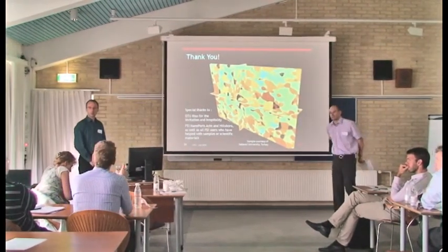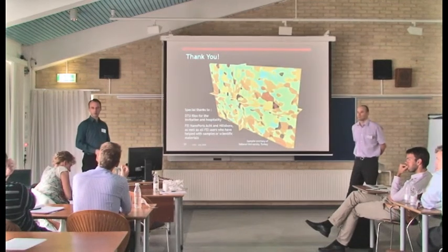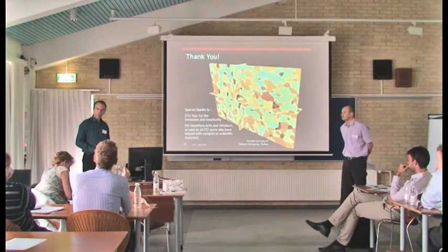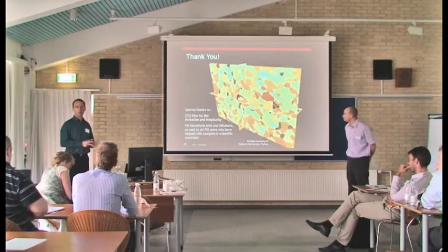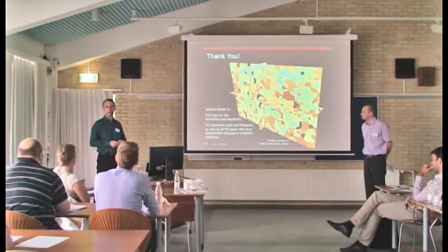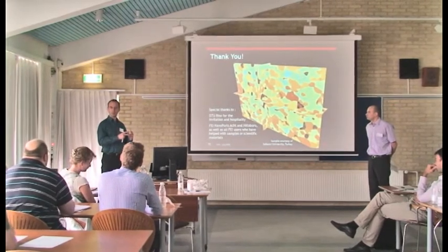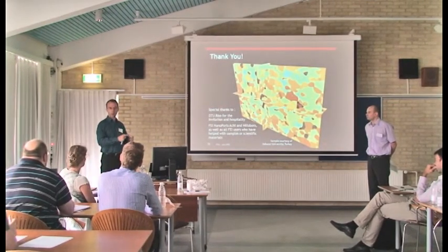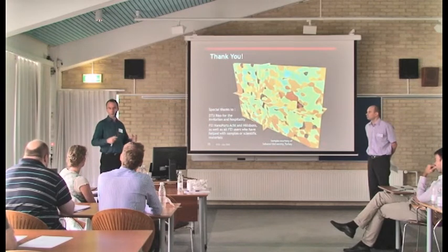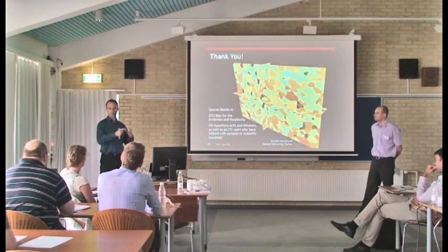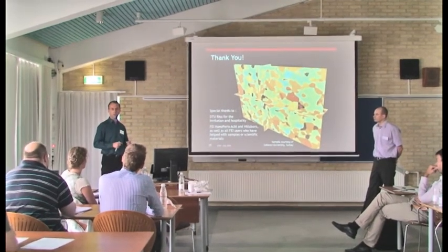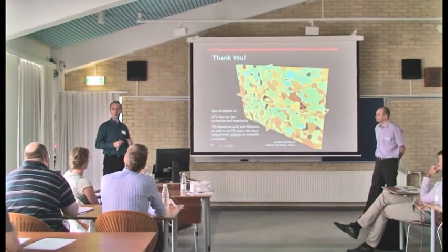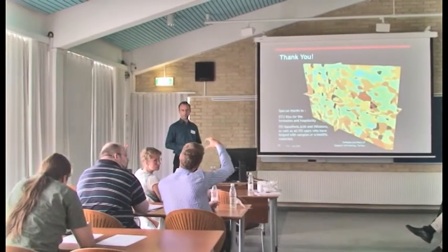Could you comment a bit on how you actually measure this slice thickness? I can explain some of it, though I have to say I don't know all the details. These are basically top-down measurements made by the focused beam at higher magnification. We take shots at every slice that we cut, at sufficient magnification, so that we can truly measure what the distance is. So you take it from the top-down view.